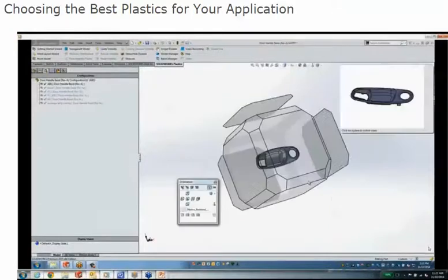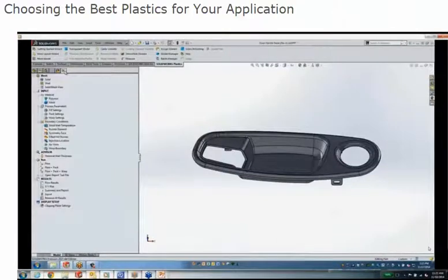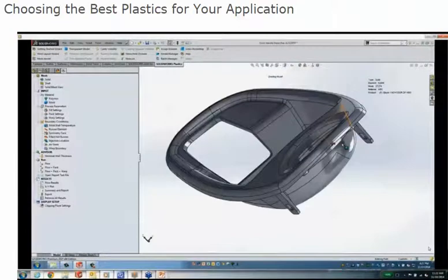So the first thing we may want to do is obviously choose a material, and next we'll choose an injection location, and we're just going to choose just over here on the side. Next we'll look at some process settings. And what we've determined here is that the injection pressure limit of 8,500 psi is appropriate. We really want to stay below 10,000 psi, so we've added a small safety factor in there just in case there's any other pressure losses further upstream in the system.